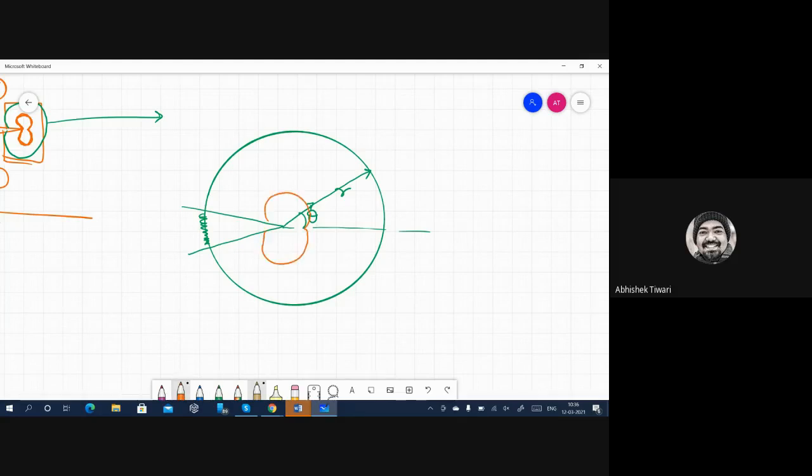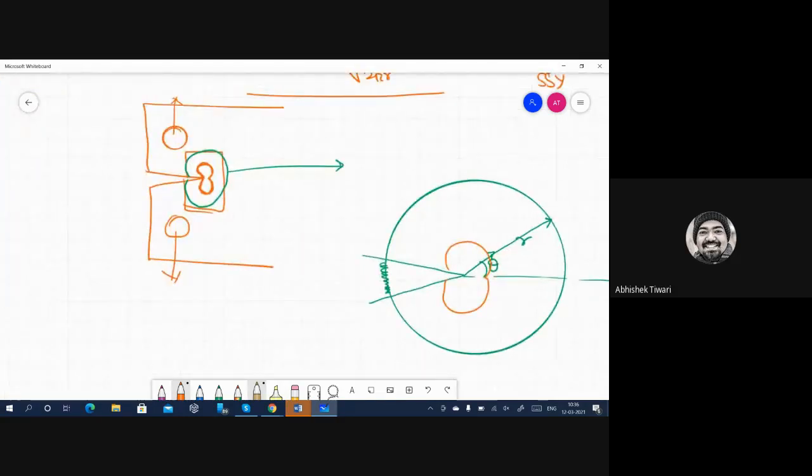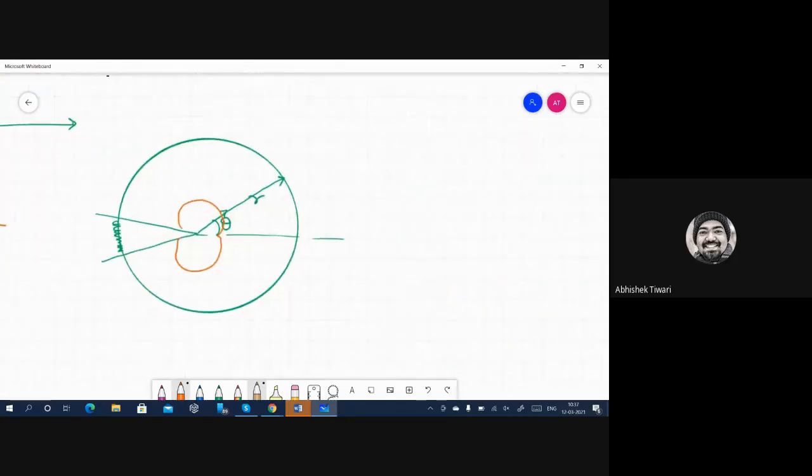I know because I have chosen in such a way that this scoop is bigger than the plastic zone. So the plasticity is somewhere inside. So what is happening at the boundary? There is no plasticity because the plastic zone is inside. So here, whatever is happening is following theory of elasticity. Okay. So very simple. It is following Hooke's law.